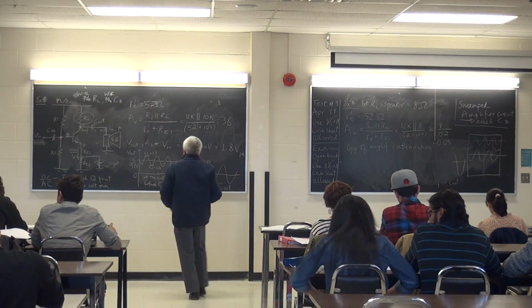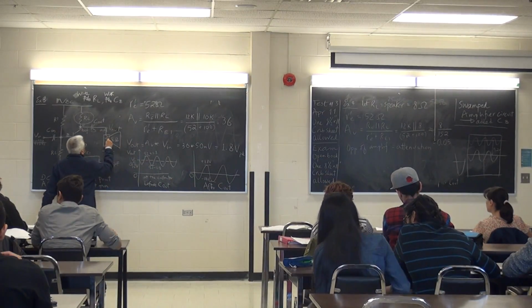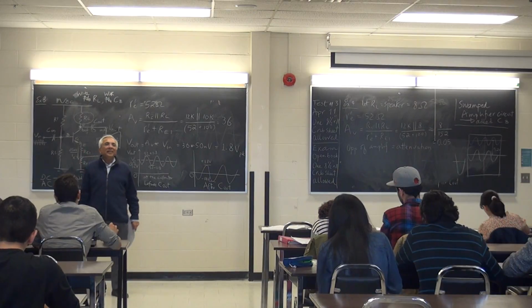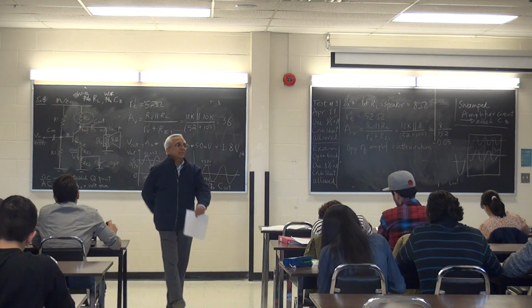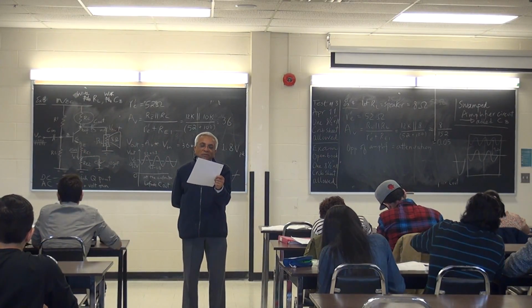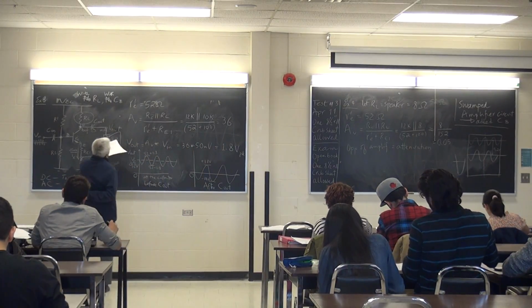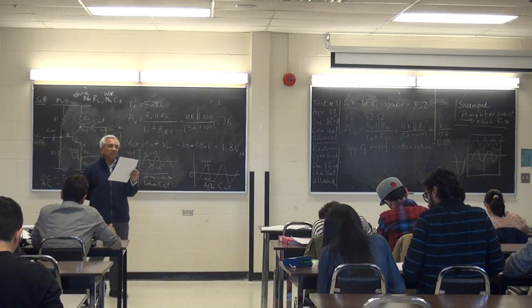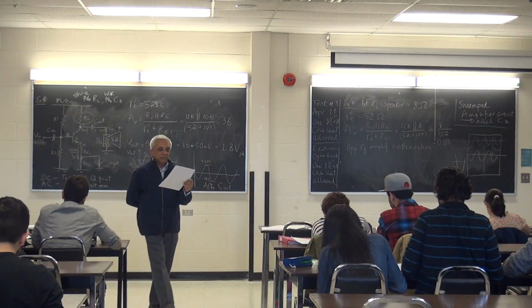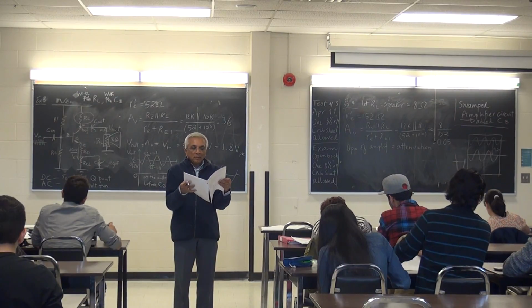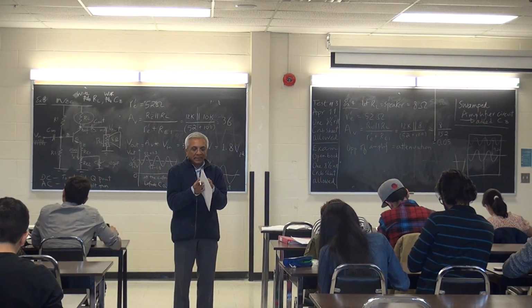Around RL, can you draw this box? So where it's RL, can you draw a box and show a speaker there? So do this. And write down 8 ohms there. Okay, that's what we're going to do with what's called a common collector amplifier circuit.